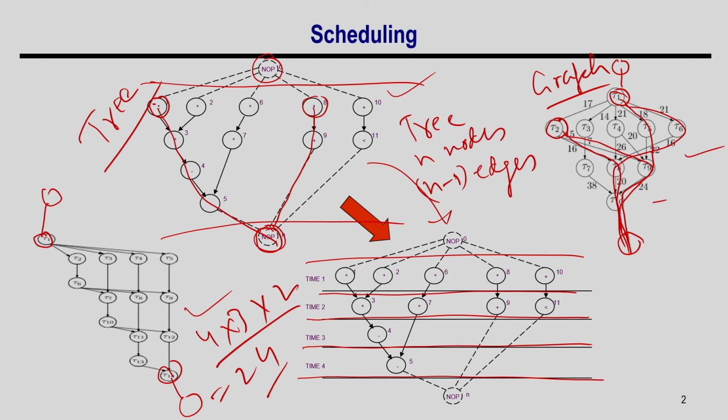Next, we have seen that the nodes can perform many operations. This one is performing multiplication, this is performing subtraction, this is performing plus, this is performing greater than or equal to, and so on. These are all different types of operations, and it is understandable that in hardware these operations are not executed using the same module. You can have different function units, like a multiplier, an adder, a divider and so on. So you have operations of different types. That is one aspect.